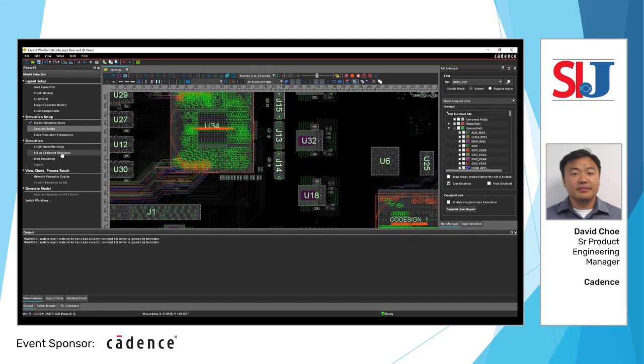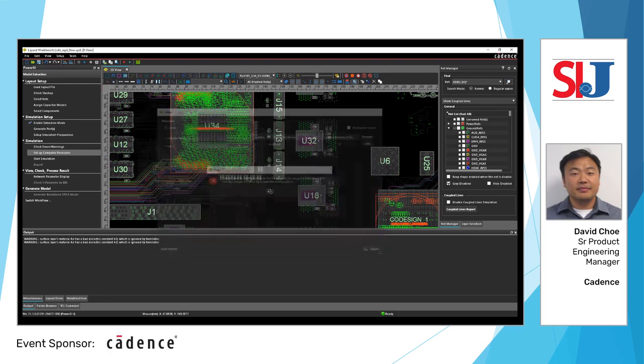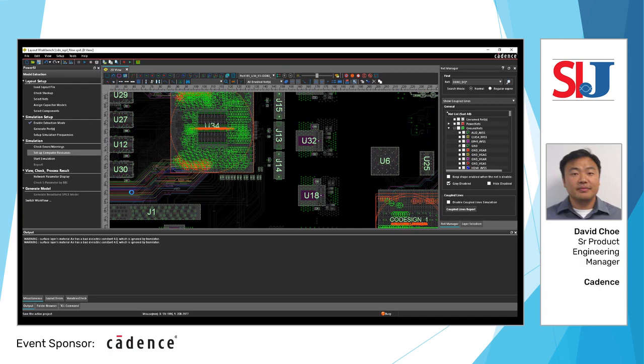Now, of course, we can set up the computer resources. In this case, I have 8 cores and 32 gigs of RAM. If this were being run on a Linux farm or a Linux server, you could do a distributed solve on a server using a queue. There are some other things coming, but in this specific case, we're running on Windows and we're going to use the local resources. So you hit OK here. You need to save this before going to anything.